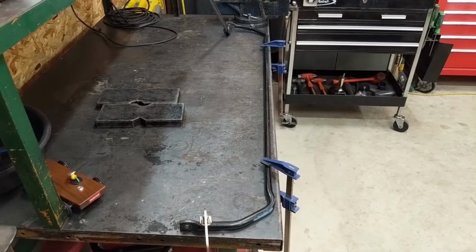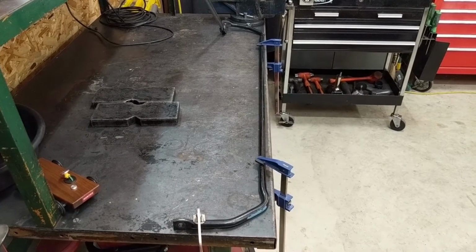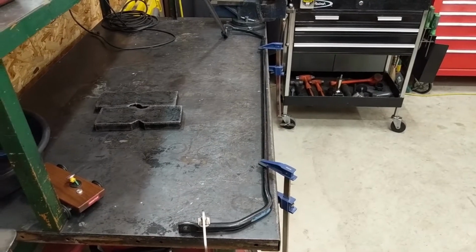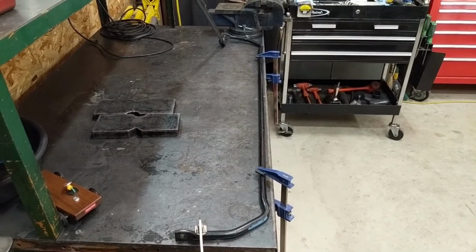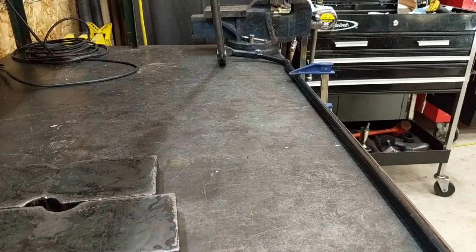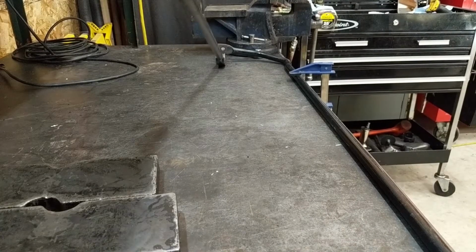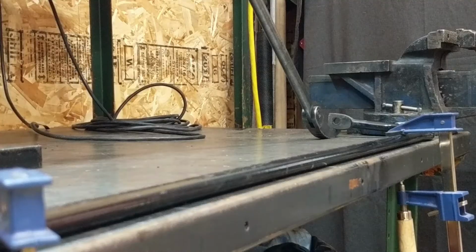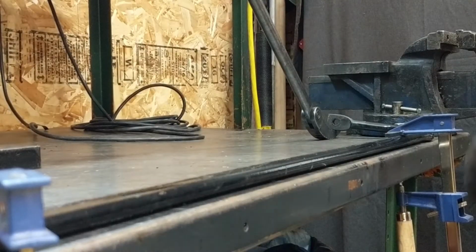So it's using the vehicle's body sway or body roll to help apply more force to the side of the vehicle that is decreasing weight on the tires, increasing stability. Now as I pry down on the pry bar here, that end of the sway bar lifts up. That energy is transferring down through the length of the sway bar.